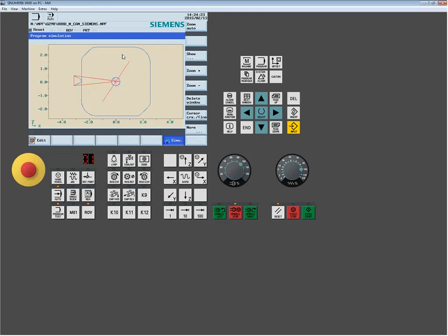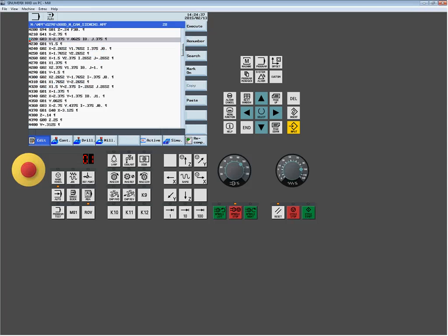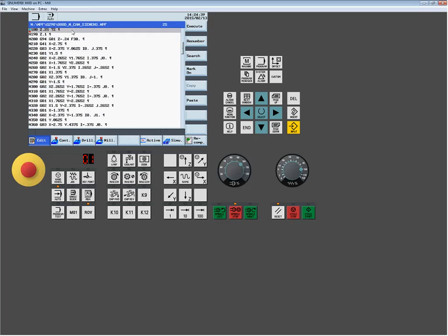Whether you use 0 offsets in the tool table, quite common, very acceptable, or use true offsets. I like using true offsets in the table. I think it makes it a little easier for operators. You know, if you're setting up a 1/2 inch end mill, put 250. And this way, if you know you're doing regrinds or it's undersized or oversized, you can put that true amount, and you're not always kind of guessing. So this would be the trick, using the TOFFR statement.